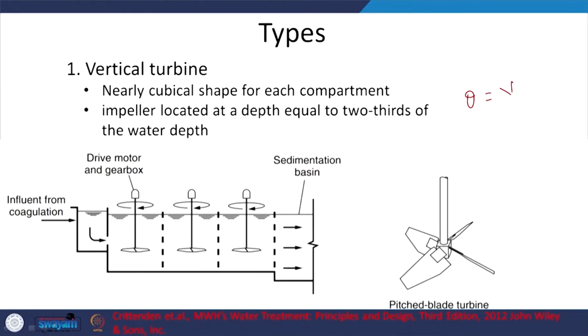Now, it is in the order of a few minutes or even half an hour, sometimes even 1 hour. So obviously, for the same flow rate, if the water has to spend more time, you need a bigger volume. Theta is equal to V by Q. If theta increases, V also has to increase.